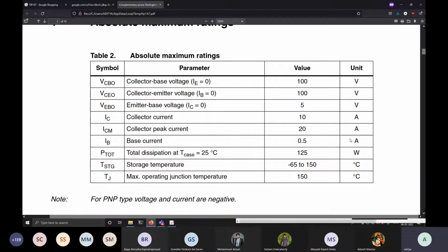But for switching MOSFETs, as you know, or as you will learn, or as you are in the process of learning in electronics, transistors are current control devices. On the contrary, MOSFETs are voltage control devices. So the dissipation that happens in MOSFETs is significantly lower. That is why if you ever want to build an H bridge driver, you rather go with a pair of MOSFETs, a P channel and an N channel MOSFET, rather than going with BJTs. But in this course, I have discussed BJTs because it is easier for me to explain without having to explain from scratch what a MOSFET is.